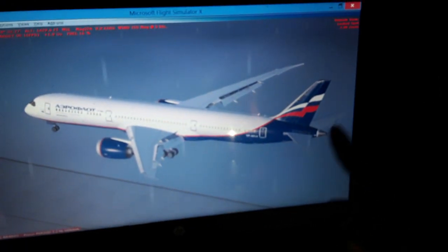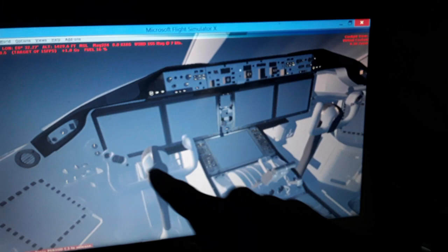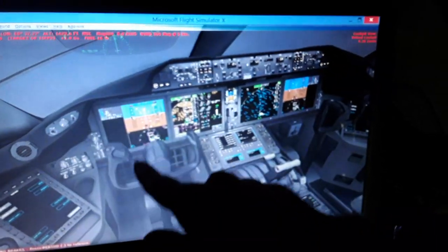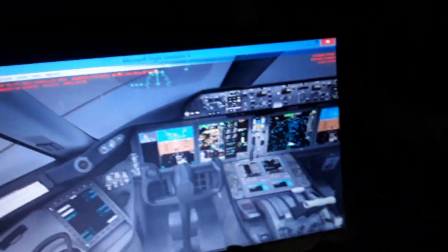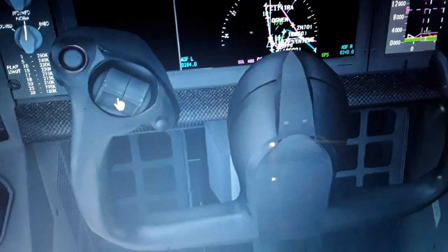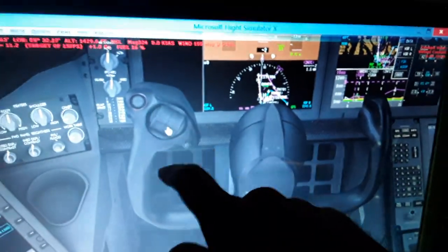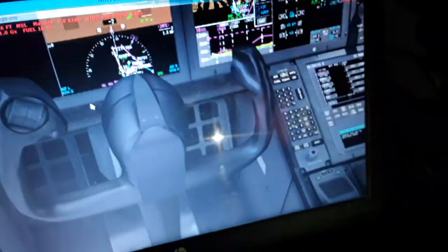I talked to you about trimming the horizontal tail in flight. This is done either manually using the horizontal trim stabilizer over here, trim switches. We can trim the horizontal tail of the aircraft like this, trim up like this, or trim down the other way. When we're doing this way, trim down. When we do the other way, trim up. So the same is displayed here.